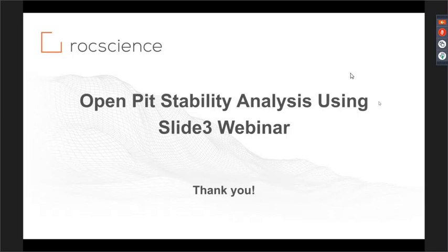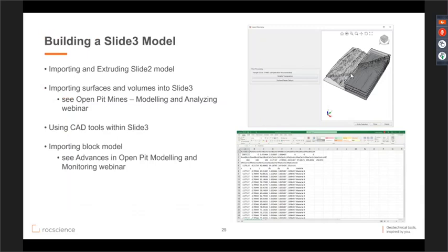It's really important, whether you're modeling in Slide2 or Slide3, I would really recommend using the show all surfaces option when you're interpreting results, to ensure, whether you're modeling in 2D or 3D, that you've adequately searched the whole section of slope that you're looking for. Show all surfaces is a nice tool that gives you a graphical display of where slip surfaces have been calculated in your model.